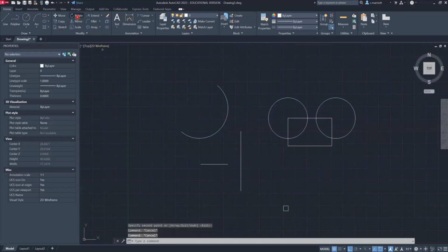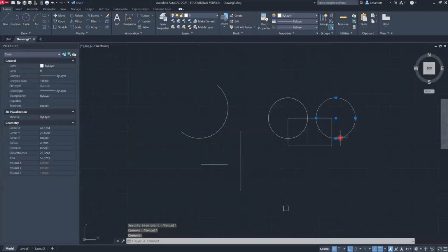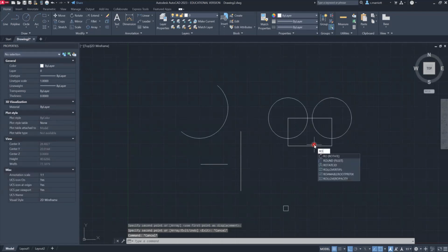Rotate. The rotate tool, as the name suggests, allows you to rotate an object. So I picked this rectangle, I'm pressing enter. And by the way, let's do this where I'm going to get rid of this one. I'm going to make a copy of my circle here, this time from one corner to the other. And now if I do the rotate command, and again, I use a lot of hotkey strokes or short strokes. RO is the same thing as clicking that rotate at the top.